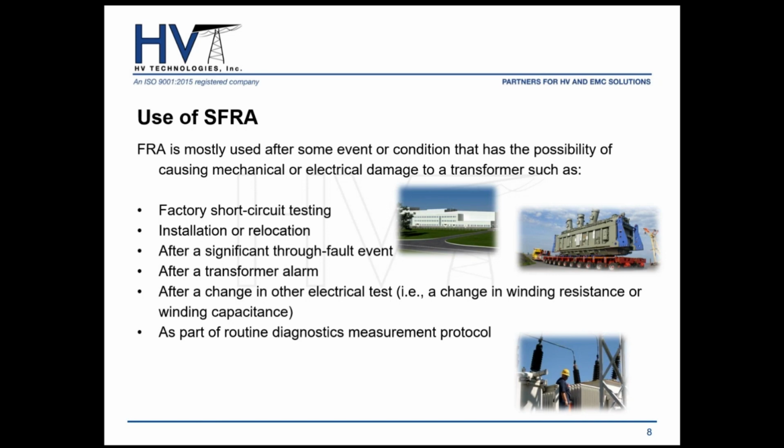Also, you may use it after a significant through-fault event, say a substation transformer experiences a short circuit condition or some sort of overloading. After the event, it is a good practice to run a sweep frequency response analysis just to make sure that everything is okay.